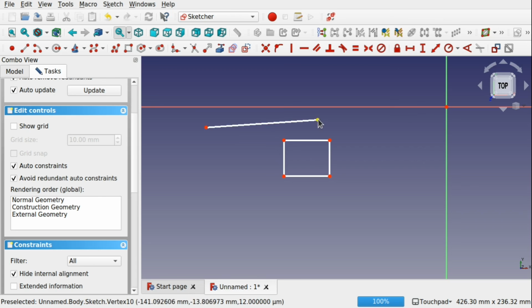Click the auto constraint, and this time when we do it, we can see red lines coming up. You can see where the pointer is, and to the right the red lines coming up, so that's the auto constraint kicking in saying it's horizontal constraint. There it's a vertical constraint, it's constrained into that line. So this helps save a lot of time.